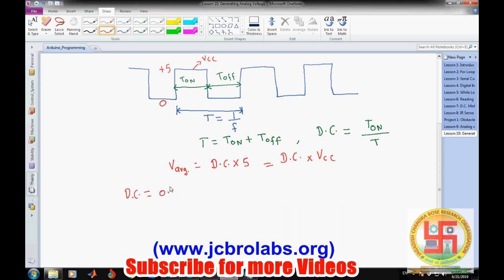If we talk about a 50% duty cycle, that means 0.5. Here we are not multiplying it by 100, though generally it is multiplied by 100. Let's say duty cycle is 0.5, that means T on is equal to T off. In this case the average value we get from this waveform will be 0.5 into VCC, 5 volt, that means 2.5 volt.